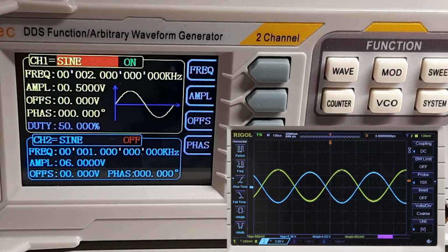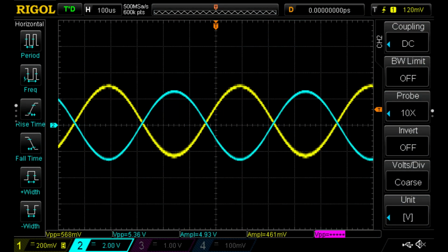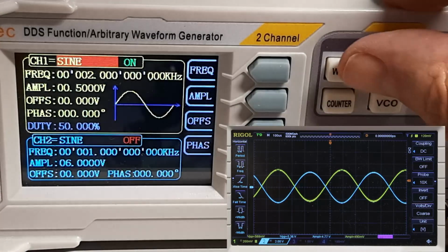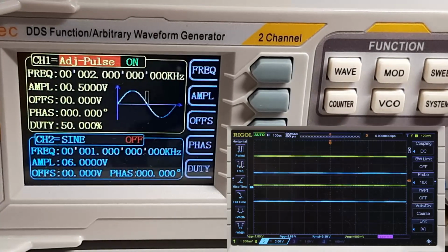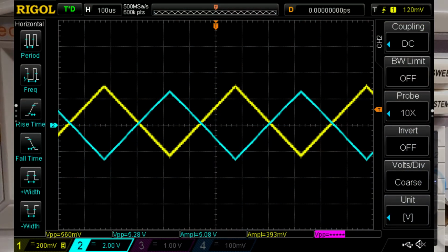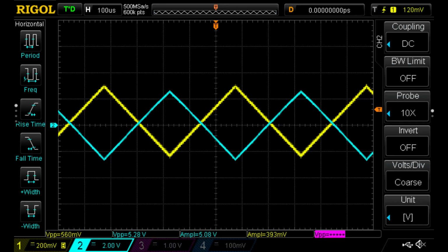I'll set up my function generator to a sine wave of 0.5 volt peak to peak, because why not? The result looks good on the scope. Trace 2 looks like a 5 volt peak to peak sine wave. I'll switch over to a triangle wave to check the linearity. It looks linear. No clipping or rounding over the peaks. It looks as if this is a working design candidate.